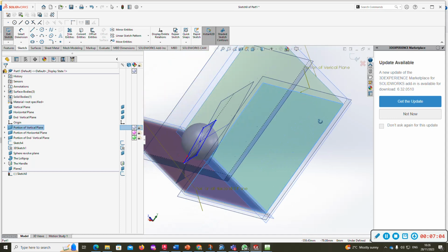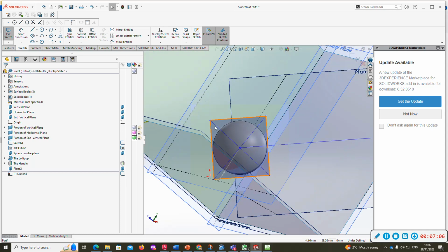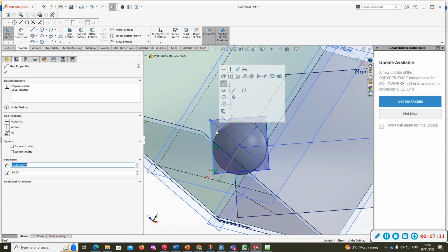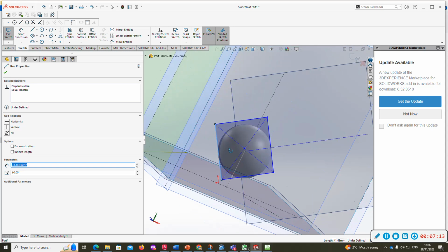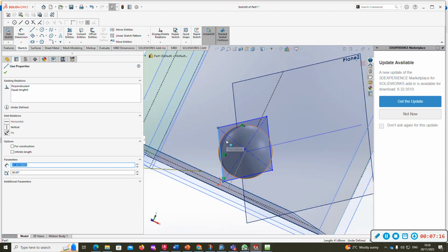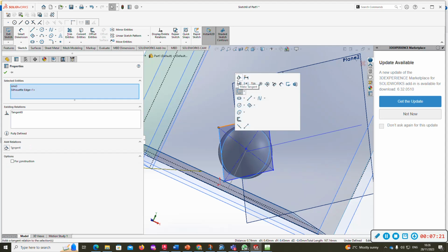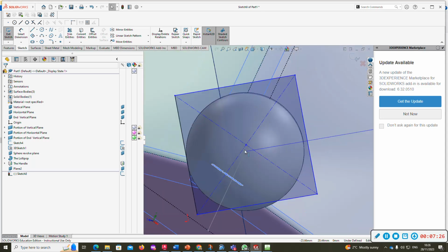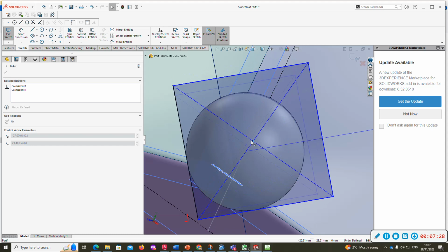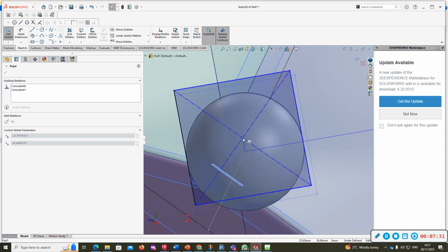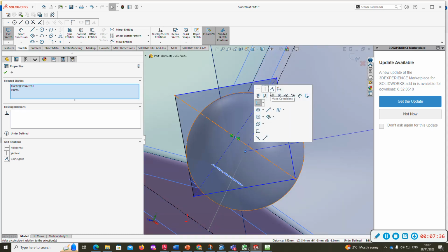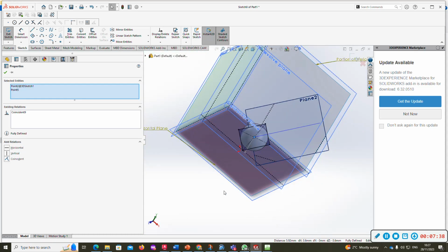They're all being really annoying to click. Okay, equals. I'm going to click the rectangle there. Now I'm going to catch the loop. See this little cylinder that comes up right there? Hold down Control, click that, make tangent. Now this square still hasn't gone blue and it should have. That's because the center is still moving about. So I'm going to click the center point, hold Control, click that point of the stick, make coincident. And now it's gone black.